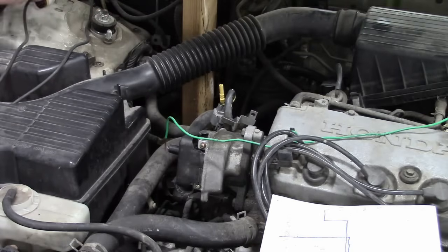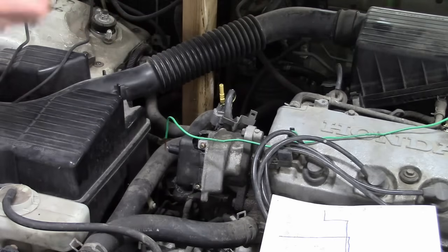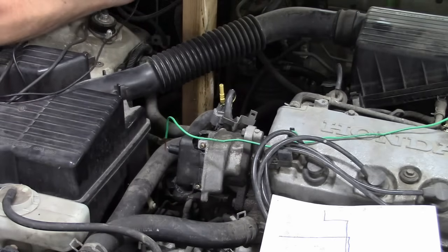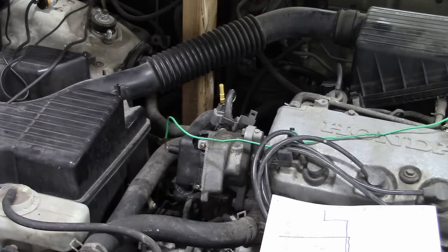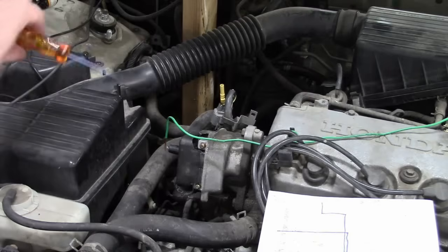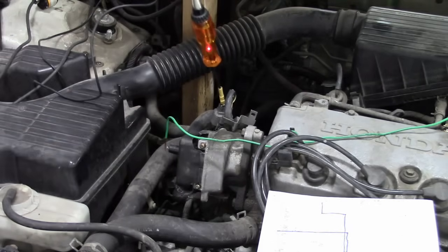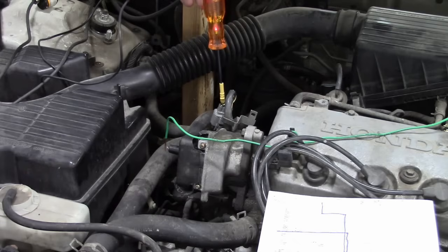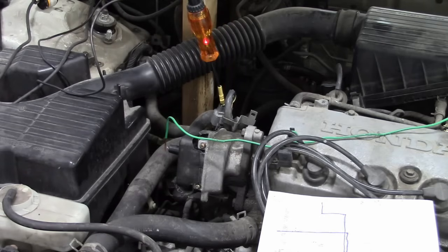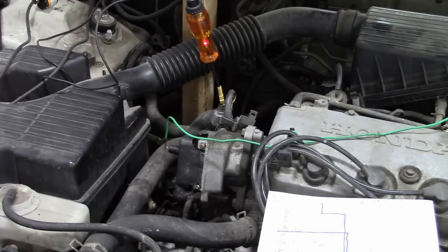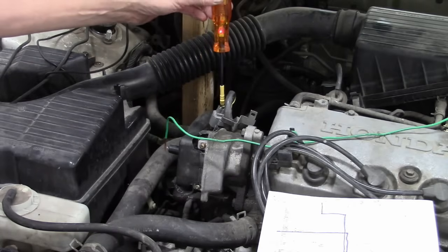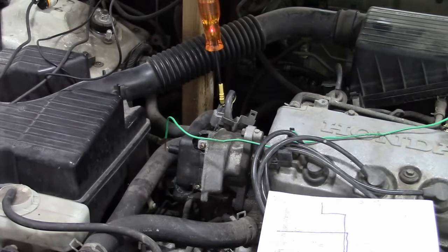That's not going to happen because there won't be enough amperage to light that light. But there will be with an LED light. So I'm going to get this LED test light and put this on battery negative. And this should flash. You can see right there, we do actually have voltage on there right now. That would not have been enough to light up my incandescent light. You need 250 milliamps to light that one up. We only need, I think, something like 20 or maybe 50, but I think it's more like 20 to light this guy up. So we're going to crank the engine and look to see if that flashes.